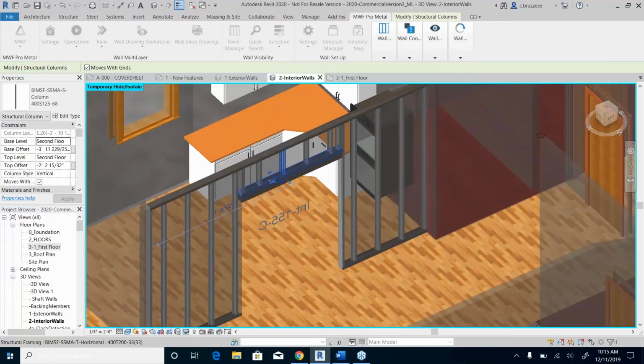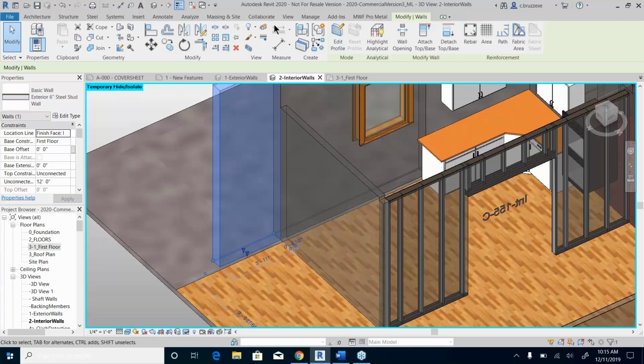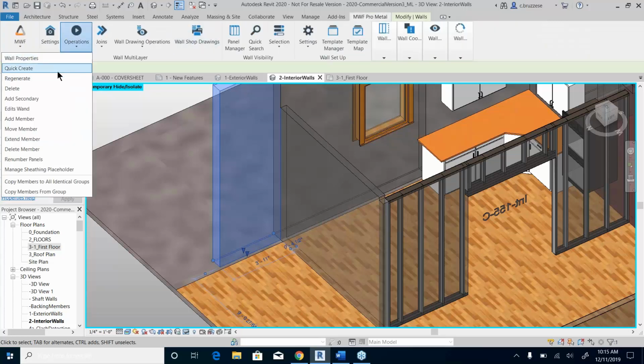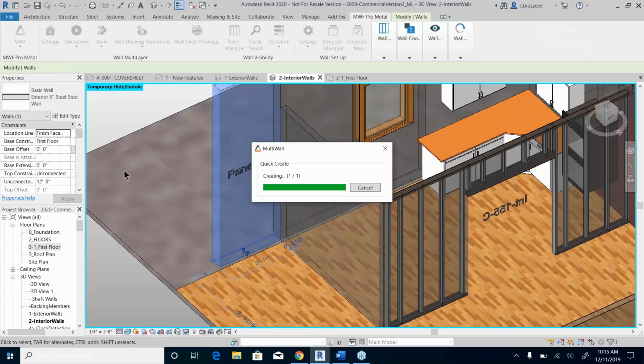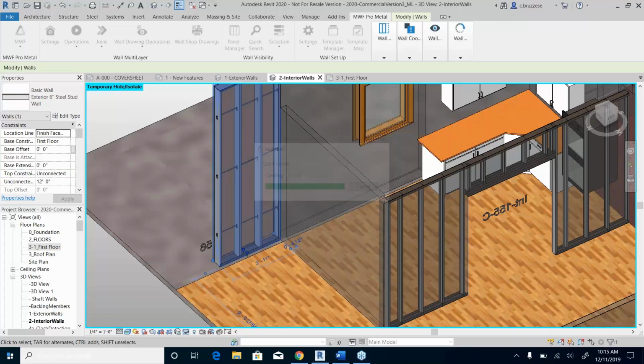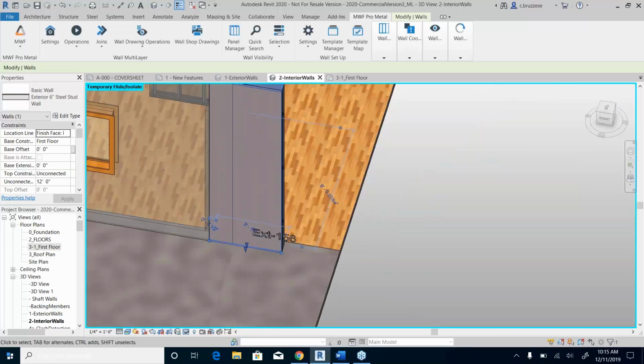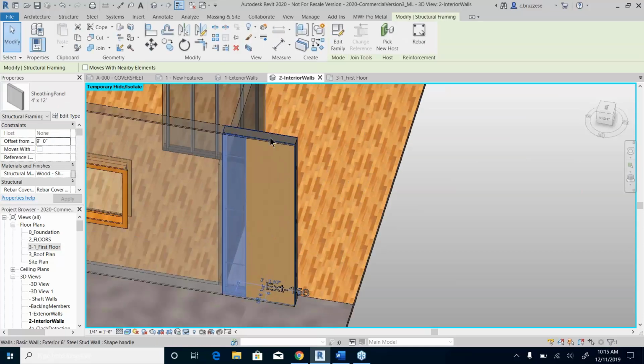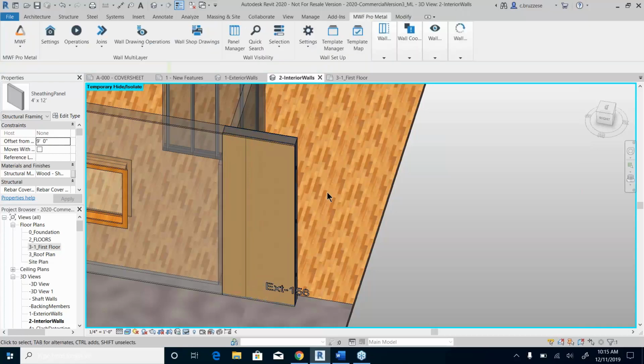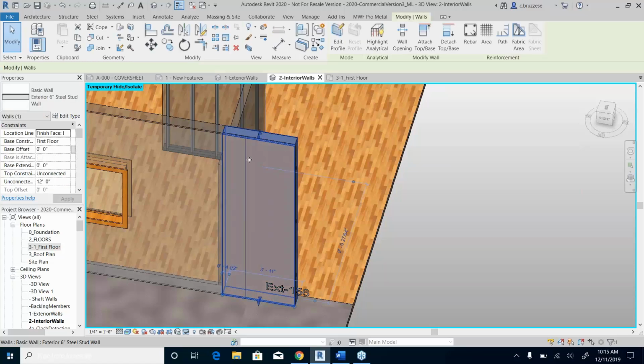So this placeholder option, relatively simple. Like I mentioned, if you do have a bit more of a slender wall, we do try and break the sheets according to the spacing. Make sure it always laps on a stud. But if you do have a smaller wall, this guy's just about under 4 feet. And I'm using 4x12 sheets.